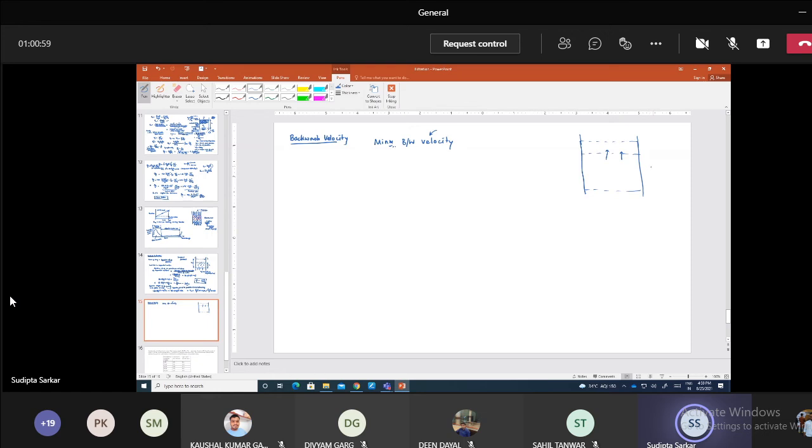It is a fixed bed initially, and when we expand this bed, this is called a fluidized bed. But before everything is fluidized, we look at the condition when it is not a fixed bed and not yet fully fluidized, but there are still particles sitting at their place. We call it the incipient fluidization condition.